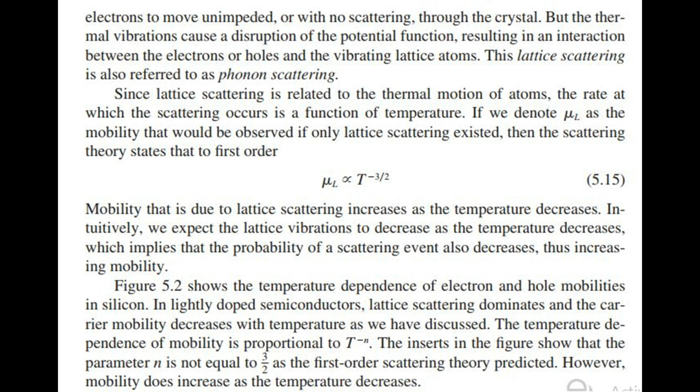Intuitively, we expect the lattice vibrations to decrease as the temperature decreases, which implies that the probability of a scattering event also decreases, thus increasing mobility. Figure 5.2 shows the temperature dependence of electron and hole mobilities in silicon. In lightly doped semiconductors, lattice scattering dominates and the carrier mobility decreases with temperature, as we have discussed.